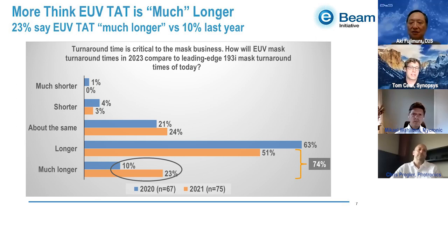On a per layer basis, the shape count will be, if it's curvilinear, 2 to 1. So let's say you're comparing a double patterning on DUV versus an EUV. Those shapes on the EUV will definitely be smaller. The wavelength is smaller, so all the granularity, all the low pass filter, loses less light there at the high wavelength. So everything will be smaller and denser, and need to be controlled to a finer tolerance.